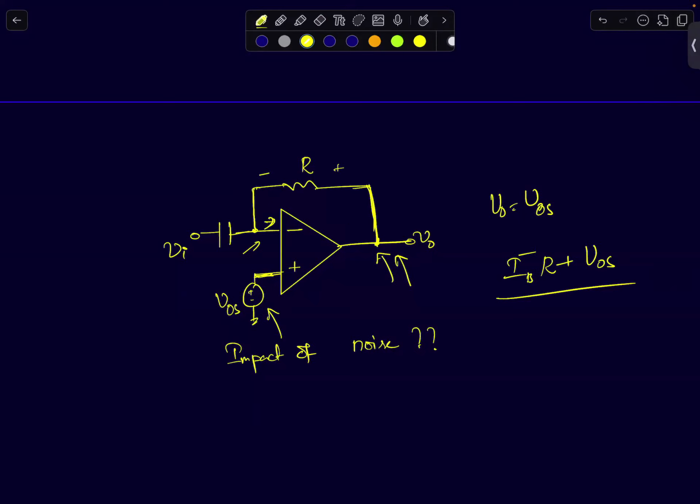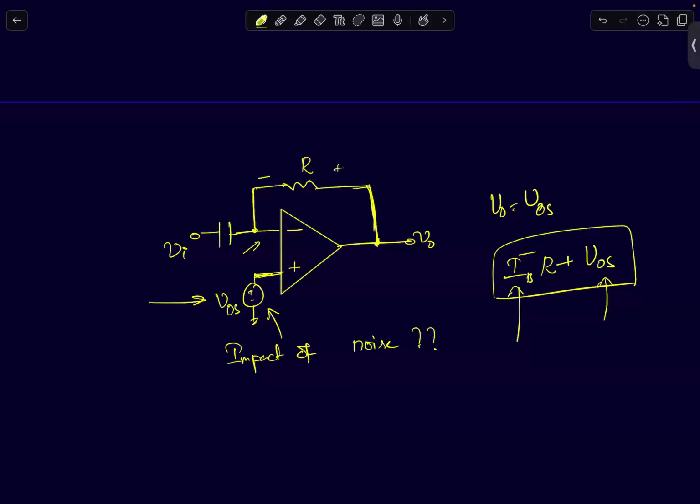We can again add some form of offset cancellation circuitry and then cancel out these offsets too. There is no big deal with that. But all I'm trying to say is that for an integrator, these DC quantities like offsets and bias currents were causing huge problems, right? They were saturating the output. But all I'm trying to show here is that it's not as big a deal for differentiators. DC non-idealities like offset voltages and input bias currents are not that big of an issue.